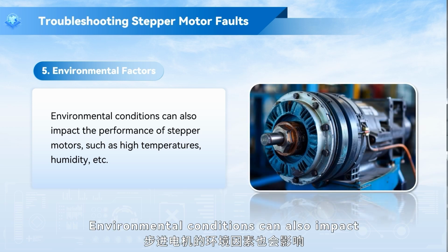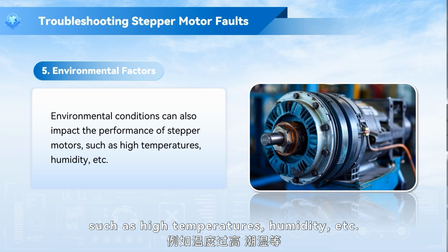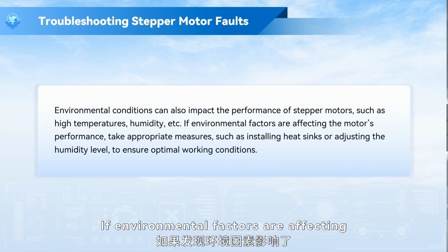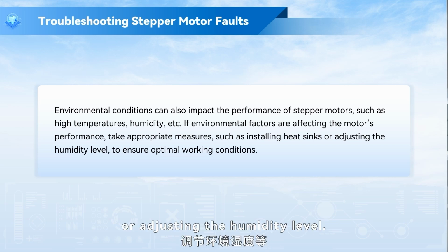5. Environmental factors. Environmental conditions can also impact the performance of stepper motors, such as high temperatures, humidity, etc. If environmental factors are affecting the motor's performance, take appropriate measures, such as installing heat sinks or adjusting the humidity level.